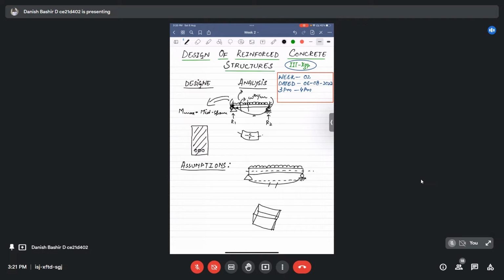If we take the beam initially and cut the cross section of the beam, we see the planes perpendicular to the axis of the beam. These would have been planes like this. And if the beam bends, this assumption makes sure that these planes, which were initially perpendicular to the axis of the beam, still remain perpendicular to the axis of the beam.